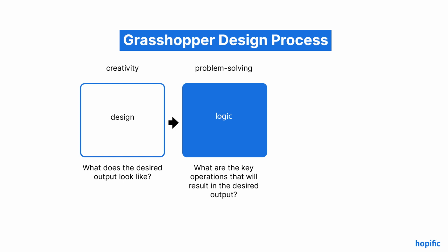For the most part, the geometric steps will be the same we would use when modeling in Rhino. But there's one major difference. While we can directly select particular objects in Rhino, in Grasshopper we'll need to express our selection in a relative way. For example, the second item in a list, or the surface facing up, or the longest of a set of curves, or the object closest to a point. Describing object selection this way means that our script will not just work for one particular input, but for any similar input, and even multiple inputs at once.